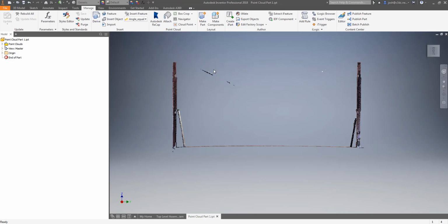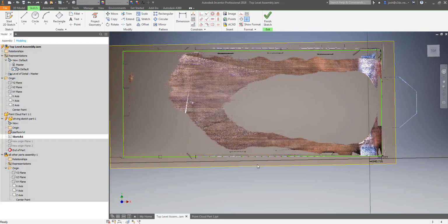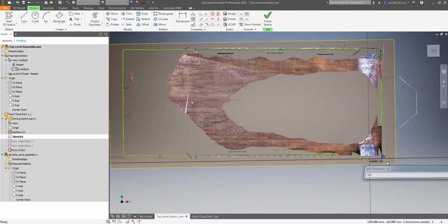Here, we are highlighting the issue long before a drawing is even started, let alone a bit of steel being cut or a crew being left standing around on site while steelwork is being modified. We'll get back to how to work out how much this is out by in a little bit, but for now, we will work on the assumption that it is more important for us to be aligned with the back wall and inside the existing walls, so we will adjust our rectangle to suit and lock it in place with some dimensions.